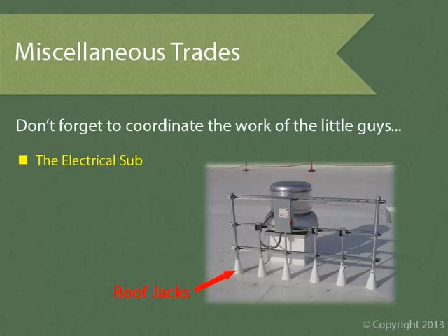We also need a 12-inch separation from parapet walls, equipment pads, and any other vertical item that you find on a roof. In this photo, you can see the contractor really did a great job coordinating the conduit penetrations through the roof. It obviously would have been a lot easier for the electrician to just bunch all these conduits together and pour a bunch of pitch around them, rather than having to construct that big rack. But to ensure a good roofing detail, they didn't take the easy route, they took the correct route.